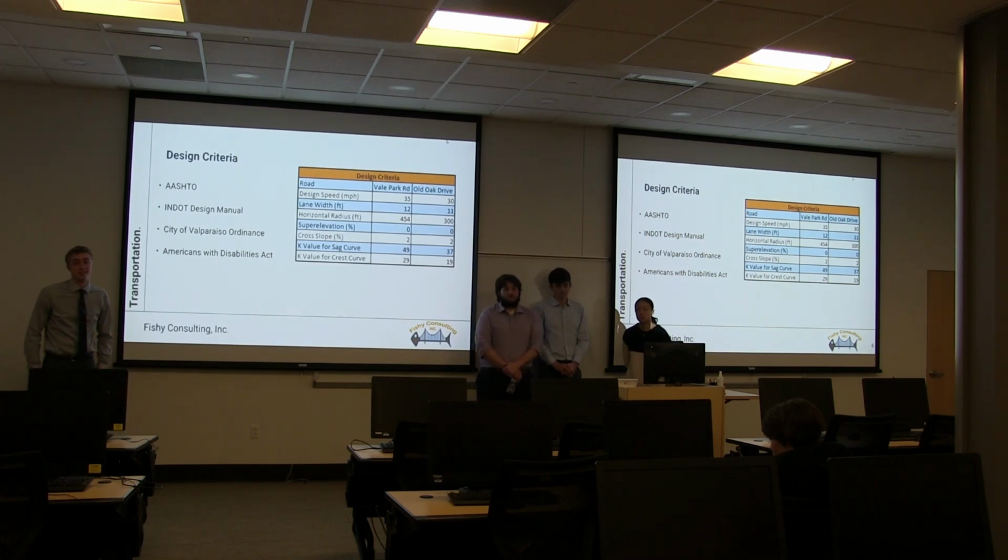And what is it, if you recall, for conveyance? If you're just using a swale to convey water, like a roadside ditch, that's a swale, so do we have to stick to the 4 inches? No, if you go back to it, the flood control depth was 1.25 feet, so you can go above 4 inches. The 4 inches was just specifically so you could get water quality treatment. And are you maintaining that in your design? Yeah, for the water quality side, yes. But for flood control, you can go above 4 inches. Thank you.